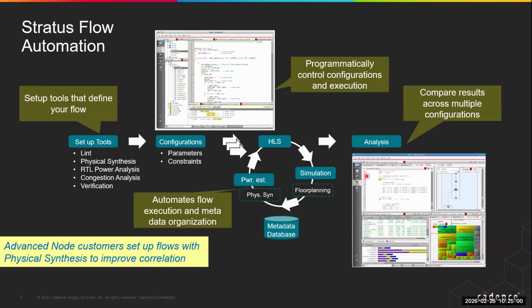At some point, you're going to need to analyze the results, and Stratus has an IDE that's purpose built to help you make sense of machine generated RTL versus a SystemC specification that drove the creation of that RTL. So you can do things like cross-highlighting from the different design representations, such as clicking on an element in a CDFG graph and having it link back to the SystemC source or the RTL. These are all supported. There's a rich set of reports, and you can click on things in the reports and have it take you back to the design and the design objects that were responsible for creating those report entries. So again, the full environment is really important, and Stratus supports automation of the flow well beyond just high-level synthesis.